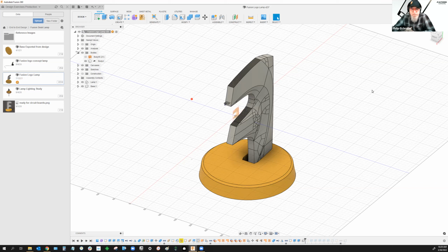So Derive can show the process of raw materials all the way through to finished part. If the casting is the source of all of that, and it has to change length because it's some kind of crank that needs to get 10 millimeters longer, then of course all of those downstream processes would update. So Derive's really powerful for showing model states. I'm sure the model state people would cringe if they heard me saying that. I'm probably using it wrong, but that's the way I think of it.